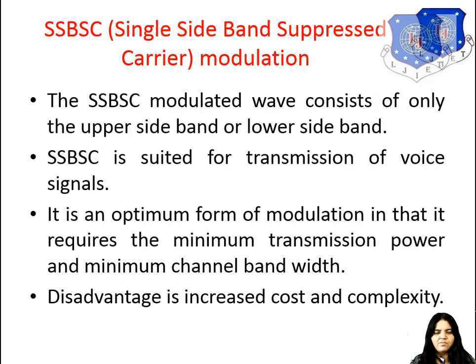The same way in SSBSC modulation. SSBSC means single sideband suppressed carrier. Now LSB and USB contain the same information. Then what can we do? We can transmit either one of the sidebands, so that we can save the bandwidth and save the transmitted power.